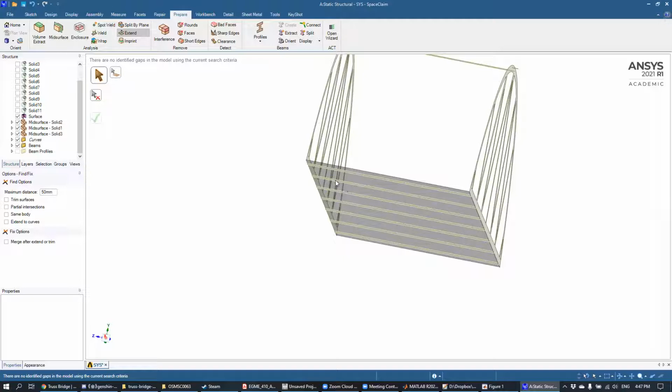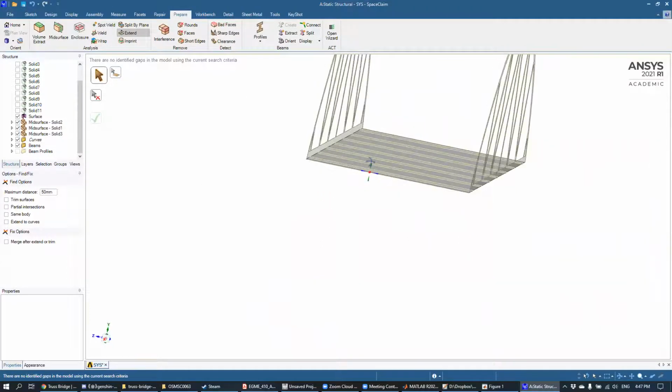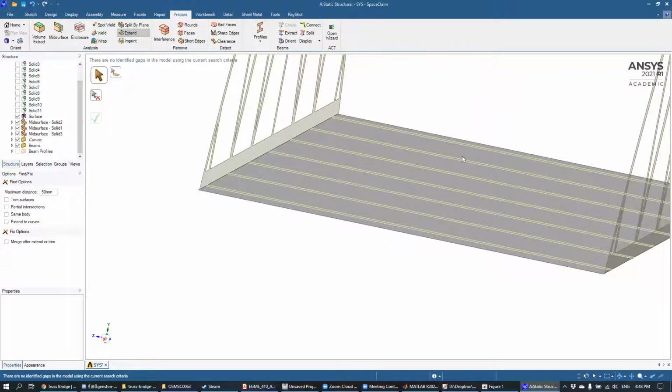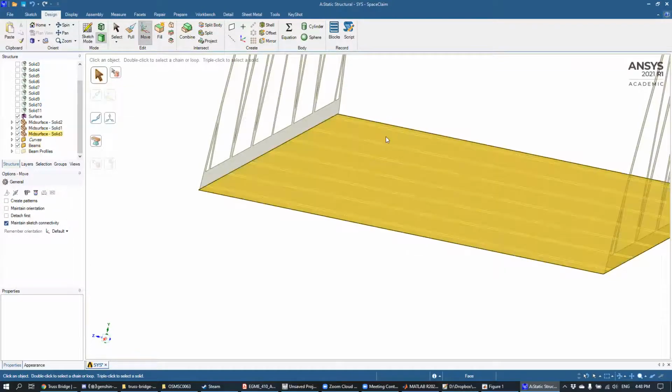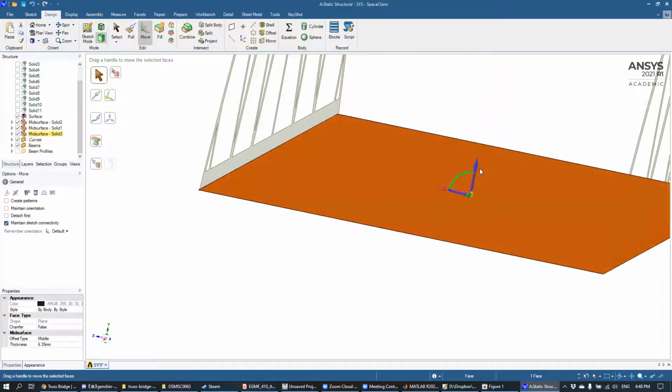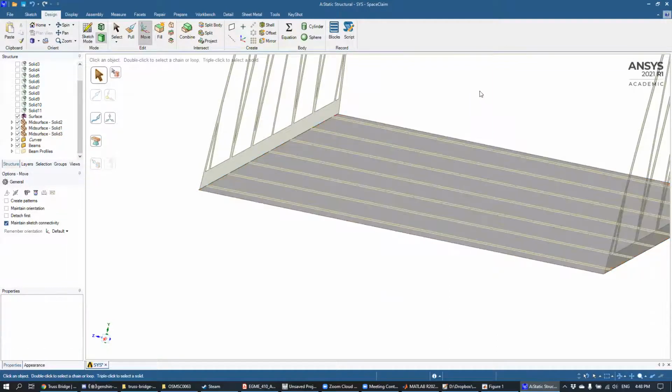Okay. So any questions on this so far? Sorry, Professor, how did you move the entire road? I accidentally just moved one side. Oh, so I clicked on kind of the middle of the road, and so when you click design and you click move, I just clicked the center of the road such that you make sure when you're mousing over it, then the entire thing is highlighted. Then you can move up and down like that. Thank you. Mm-hmm.